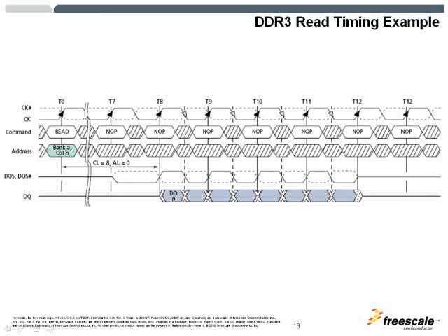There is basically no difference between DDR2 and DDR3, except a few detailed differences. The difference is that the number of beats in DDR3 is always 8 beats. And as you can see, once the read command has been issued, there are 8 bursts happening.